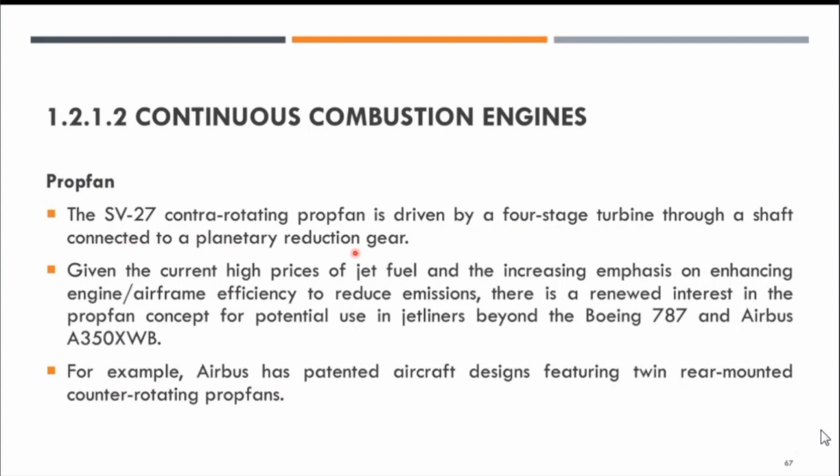Given the current high price of jet fuel and the increasing emphasis on enhancing engine and airframe efficiency to reduce emissions, okay, there is a renewed interest in the prop fan concept for potential use on the Boeing 787 and the Airbus A350 XWB aircraft. For example, Airbus has patented an aircraft design featuring twin rear-mounted counter-rotating prop fans.